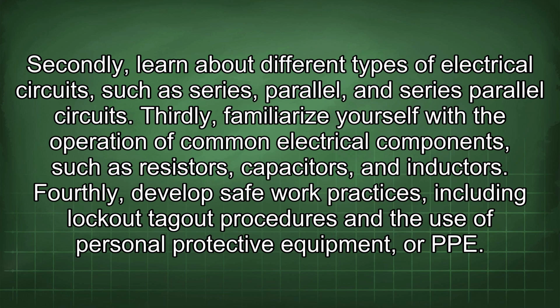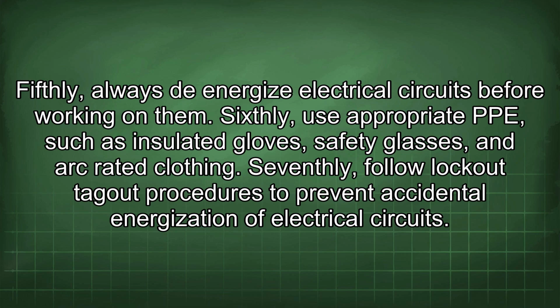Fourthly, develop safe work practices, including lockout-tagout procedures and the use of personal protective equipment, or PPE. Fifthly, always de-energize electrical circuits before working on them. Sixthly, use appropriate PPE, such as insulated gloves, safety glasses, and arc-rated clothing. Seventhly, follow lockout-tagout procedures to prevent accidental energization of electrical circuits.